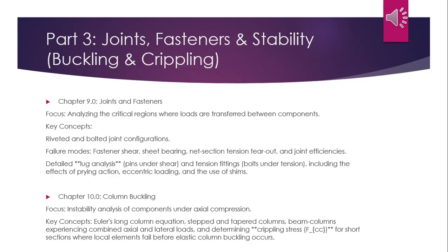Then there's chapter 10, column buckling. It's about instability analysis of components under axial compression. The key concepts are Euler's long column equation, stepped and tapered columns, beam columns experiencing combined axial and lateral loads, and determining crippling stress for short sections where local elements fail before elastic column buckling occurs.